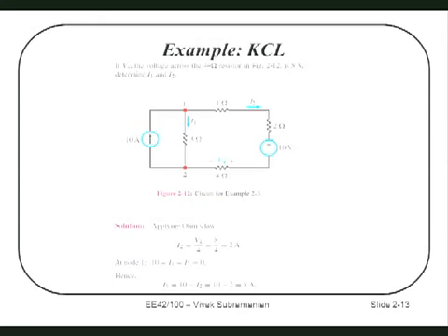This voltage source, really, if you were to ask what it does, it reduces I2. Because there's some voltage that's fighting against the higher voltage. Did we factor it into our calculation? Yeah, we did. We factored it into our calculations because the fact that there is 8 volts across here only happens if this were a 10 volt source. If this 10 volt source were not there, let's say it was a 0 volt source, we would actually have a larger voltage across here.